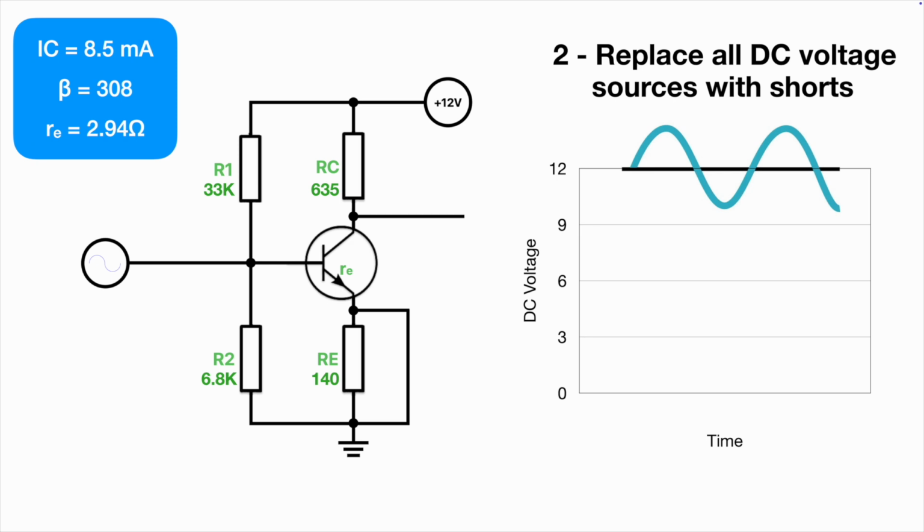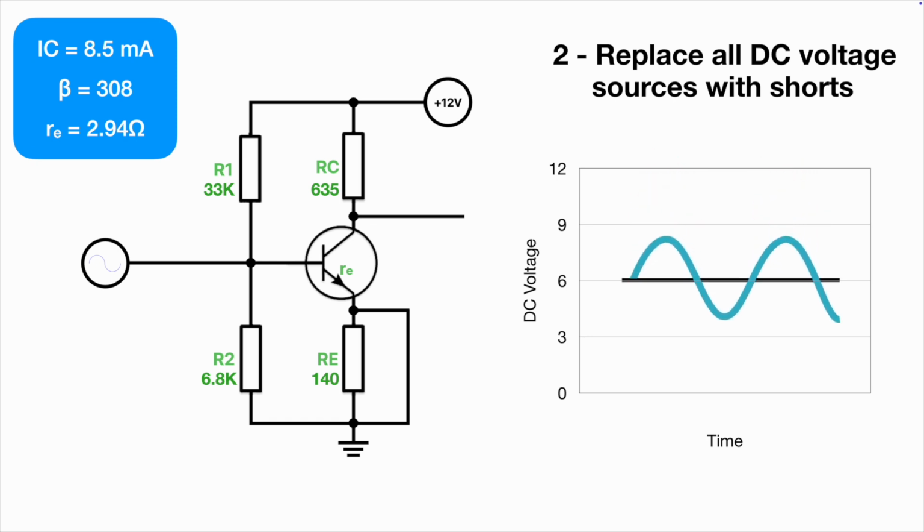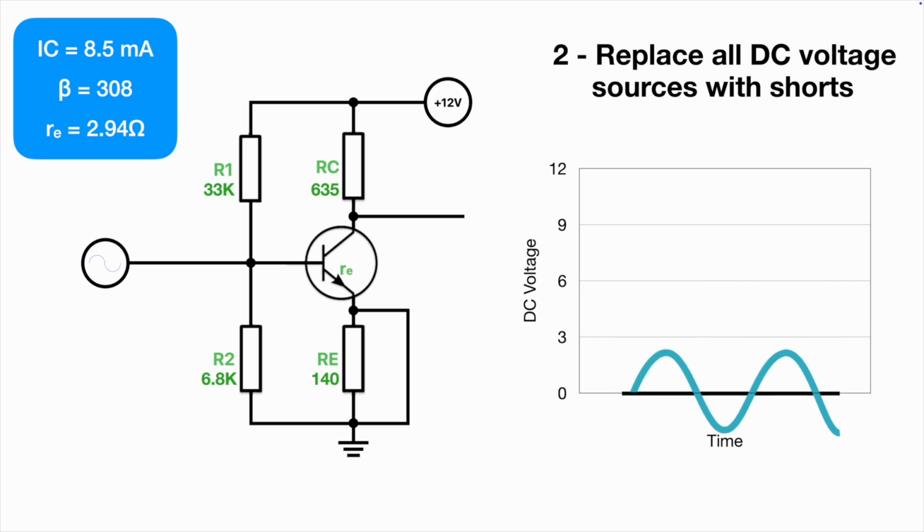Now, what I need to just say here as well is I'm not talking about the way the signal goes through the transistor. Clearly, as we spent the whole of the last video looking at, DC biasing is really important. And it does make a difference, because if you don't have it high enough or low enough, you'll get clipping. We're not talking about the transistor. We're talking about how the AC signal sees this DC voltage source. And all it sees, if you had a bias level of 12, it would sit on the 12 volt line. But if you reduce the bias to 6, it would sit on the 6 volt. There's no difference, right? Or if you grounded it at 0 volts, it would look the same.